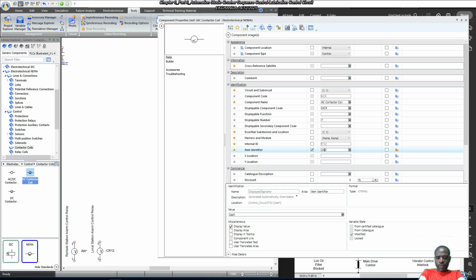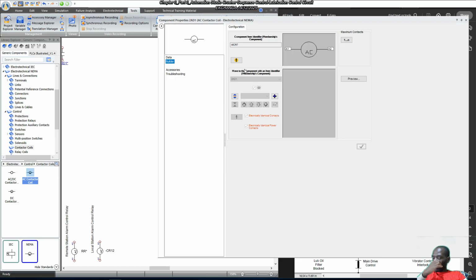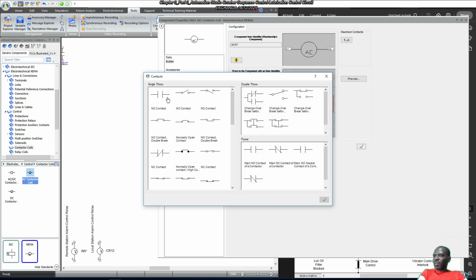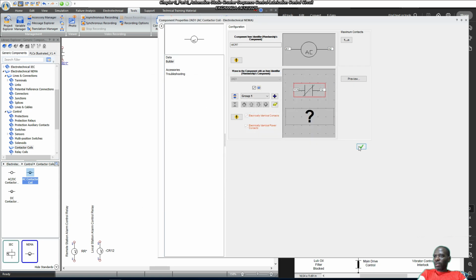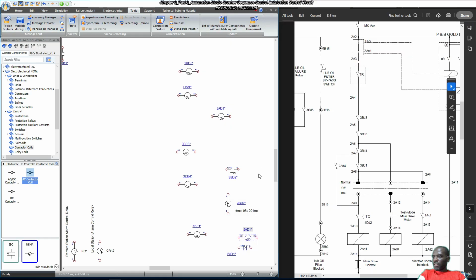I need all caps for 281. And then if this is 281, we need an associated normally closed contact, okay? And then I guess you're asking, but why does it have to be a normally closed contact? I got you, okay? So we go to 281 and this associated normally closed contact.